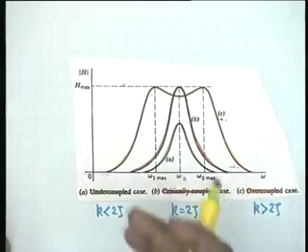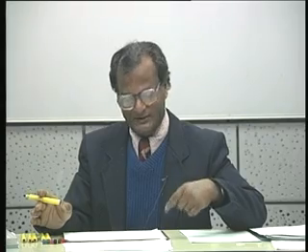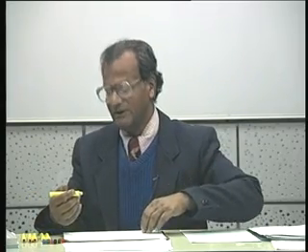It can be physically observed. It takes very little hardware to actually carry out the experiment. There are coils in the laboratory. You go to the electronics lab, ask for 2 coils, bring them close together, put identical capacitors in the circuit. Don't use any external resistance, because the coil resistance is enough to take care of the capital R, and then you can actually observe this double peaking.